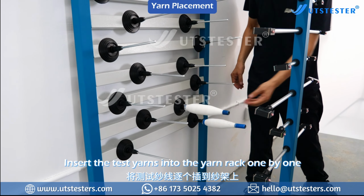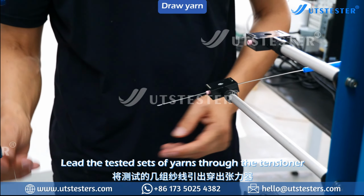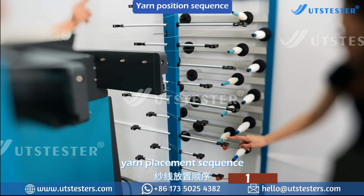Insert the test yarns into the yarn racks one by one. Run a hook needle through the tensioner. Let the tested sets of yarns through the tensioner. Yarn placement sequence.